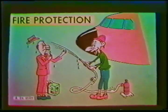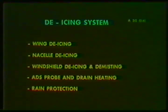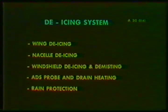This concludes the presentation of fire detection and protection systems. Let us look at the A300 ice and rain protection system now. The units in the de-icing system are wing de-icing, nacelle de-icing, windshield de-icing and demisting, air data system probes, wastewater drain and heating and rain protection.